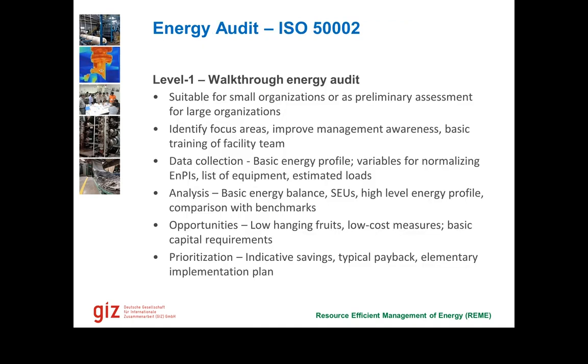Energy audit, on the other hand, as laid out by ISO 50002, talks about a much more detailed energy assessment. So level 1 is a walkthrough energy audit, which is suitable for small organizations, or if it's a big organization, we could use it as a preliminary assessment. And I'm sure you already do it before starting an audit. You go to the factory, do a walkthrough, take a note of what are the areas that you have identified, which are the focus areas we need to work on.